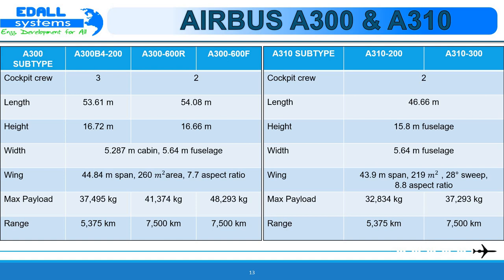The next variant is the A310-300. It provides an increased maximum takeoff weight and an increase in range provided by additional center and horizontal stabilizer, that is trim tank, fuel tanks. This model also introduced wingtip fences to improve the aerodynamic efficiency. It is a convertible passenger cargo version. The seats can be removed and cargo placed on the main deck. A310-300F is the freight version of A310-300. Operators such as FedEx Express acquired these by modifying ex-passenger A310s, usually starting with the A300 versions.